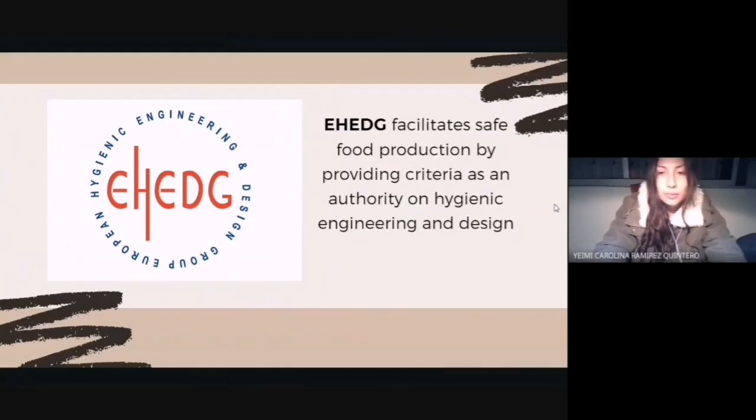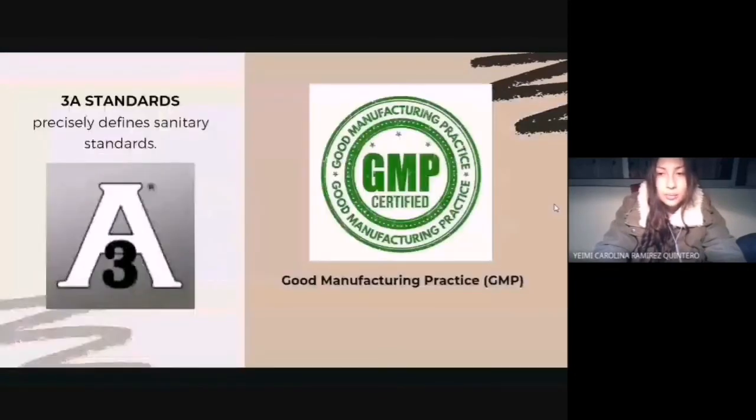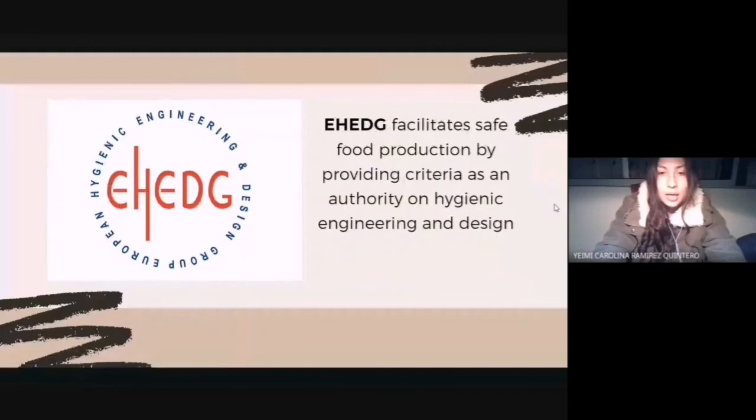Surfaces in contact with the product must have number 4 surface finish and be free of imperfections such as pits, deformation, and cracks. All surfaces, valves, pipes, and equipment in contact with the product must be easily cleanable. Their inspection must be quick. They must meet the requirement of being easily removable. And next, please.